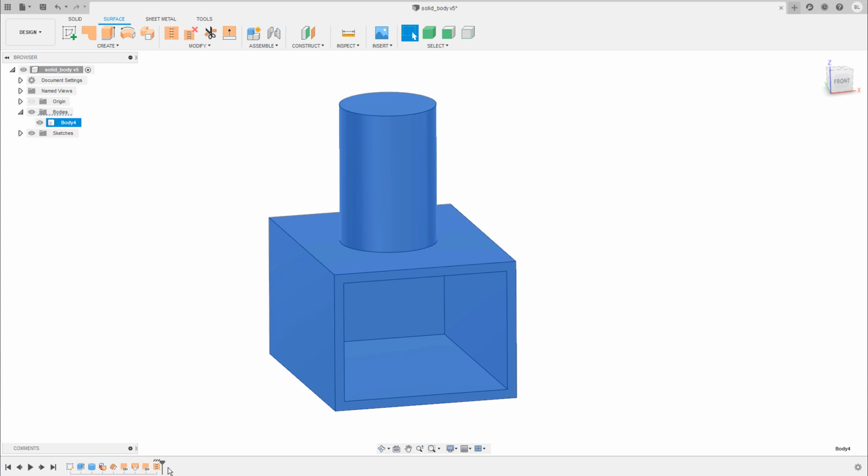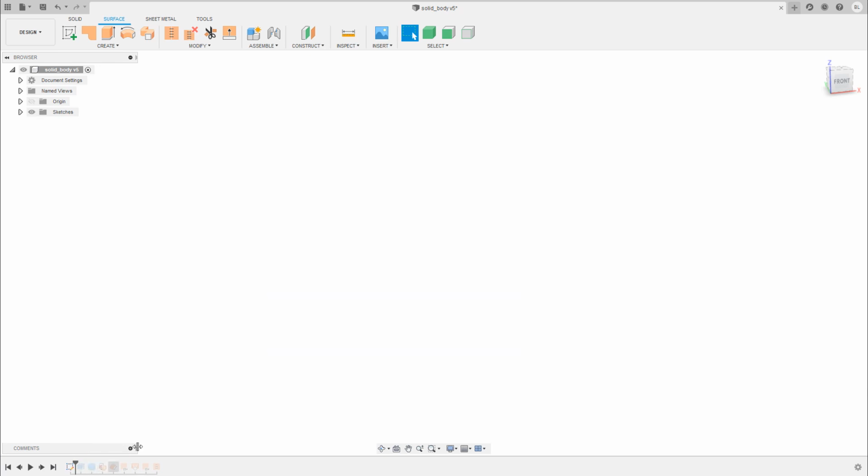And I'm talking about this little toolbar down here, and as you have probably already noticed, it gets longer and longer with each operation I perform on the model, and it actually captures everything I do. So it allows me to scroll back in time, so to speak, and to make changes on the very first sketch, for instance, or the offset that I have performed, or the stitching or the loft that I have created. So I can drag this little line back in time to the initial sketch. So let me show the sketch.